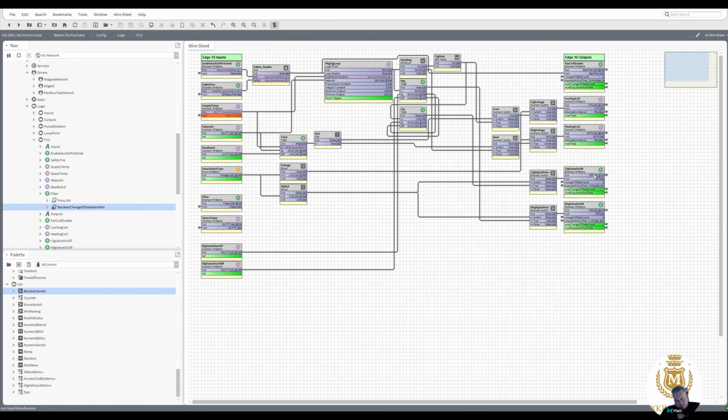Saying that, the old fan coils, the very old ones, they didn't even use heating coils. You had a cooling coil and a heating coil running all the way through all the time, and a damper that actually redirected the flow through either the cooling coil or the heating coil, like an on and off depending on the temperature.